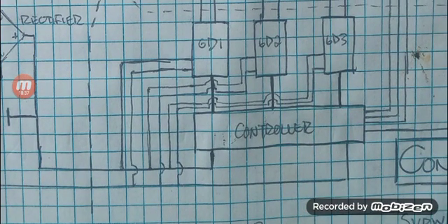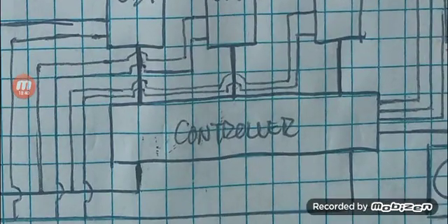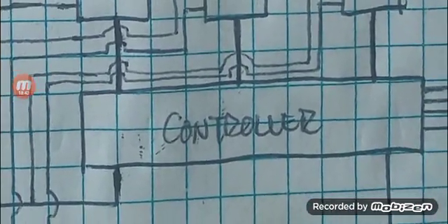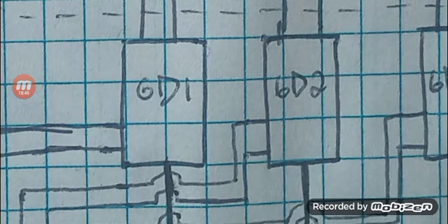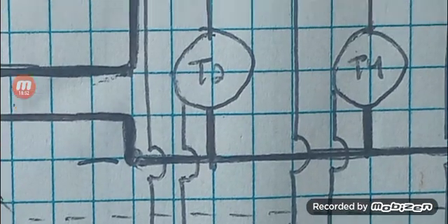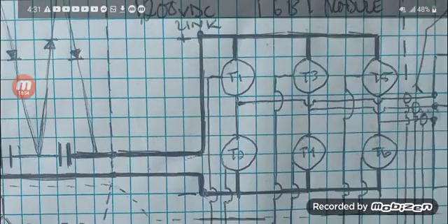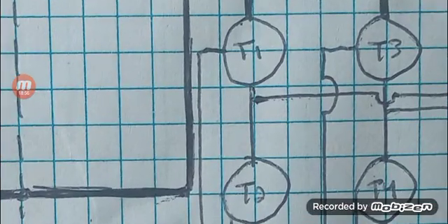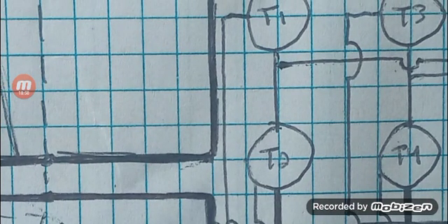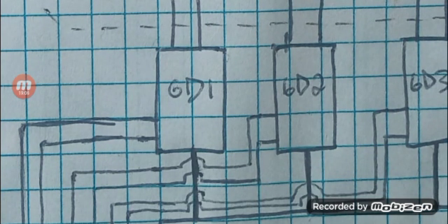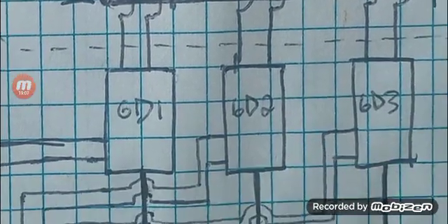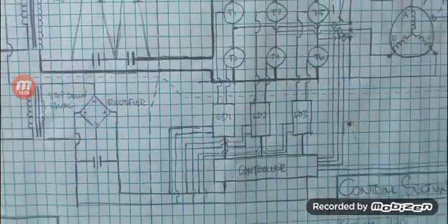Your controller is what holds your sequence, and it delivers a low voltage signal to your gate drivers, which step up that low voltage signal to a little bit higher voltage, but still low, and it feeds the signal to the high voltage transistors. These gate drivers have protection built in so that high voltage doesn't feed back. That's basically their purpose.